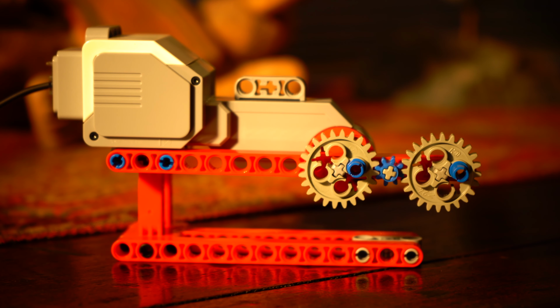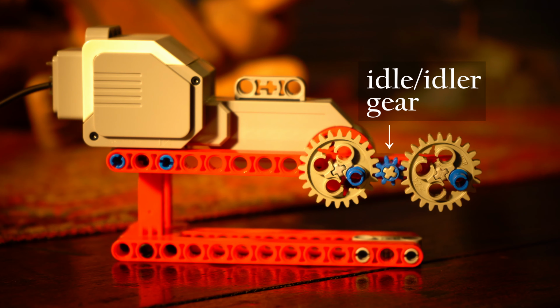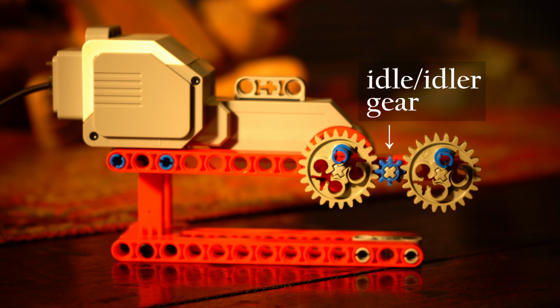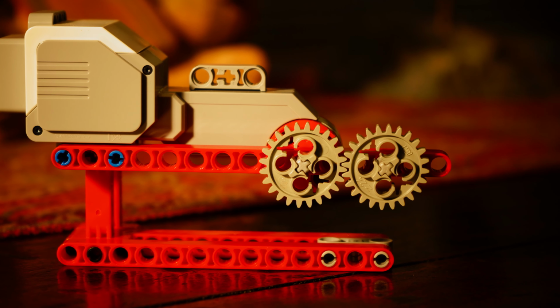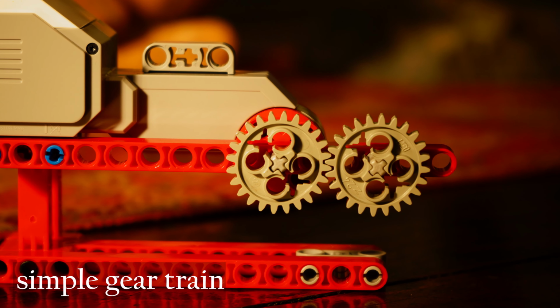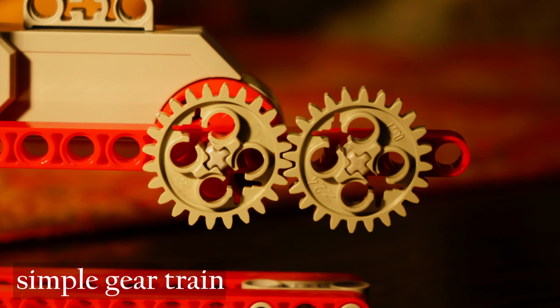If one or more additional gears sits between the driver and driven gears, these middle gears are known as idle gears or idler gears. Here, the idle gear in the middle may have been placed to enable the driver and driven gears to rotate in the same direction. Among other classifications, gear trains are often distinguished as being simple, compound, or epicyclic. A simple gear train comprises two or more gears interacting with each other in which each axle has only one gear. The previous examples have all demonstrated simple gear trains.